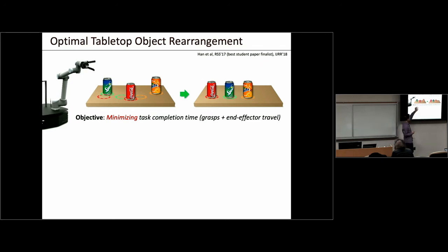What that means is that if you want to solve this problem, you have to lift one of these and put it somewhere else, right? This increases the number of grasps you have to do. As it turns out, this problem is equivalent to a well-known hard problem called the feedback vertex set problem. And this problem is actually very, very hard to solve, even for very, very small instances. And after you untangle all these dependencies, you are still left with another hard problem, that is the traveling salesman problem, for your end effector to move around.